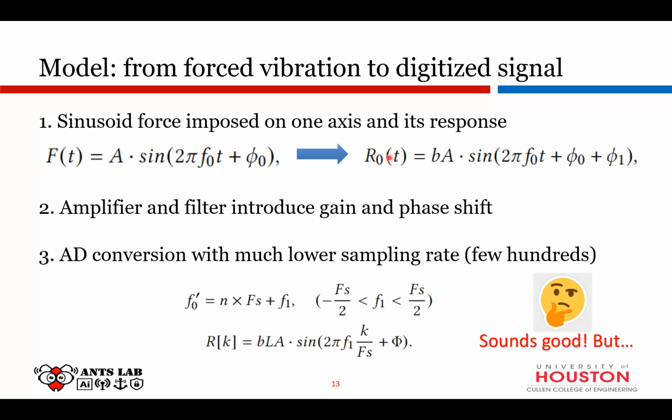But because this is a very narrow-band signal, we can adopt Nyquist passband sampling, and this frequency impulse in the frequency domain will fall into the n-th Nyquist sampling region, and at last, in the digital frequency domain, it will end up at the frequency f1.